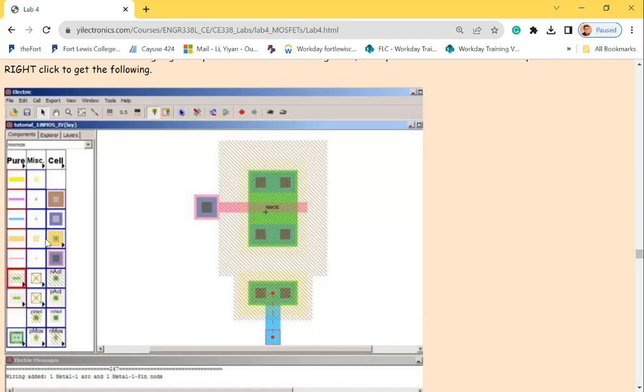And after you grab this one, you move them close enough so we can see the dashes are overlapping with each other. In that case, it's not going to report any errors. If you don't overlap them, it's going to report errors. Keep in mind, you don't need to electrically or physically short anything together. You just grab one of these and resize it, and then move it close enough so the dashes overlap. Done. So you are not going to get any errors reported.